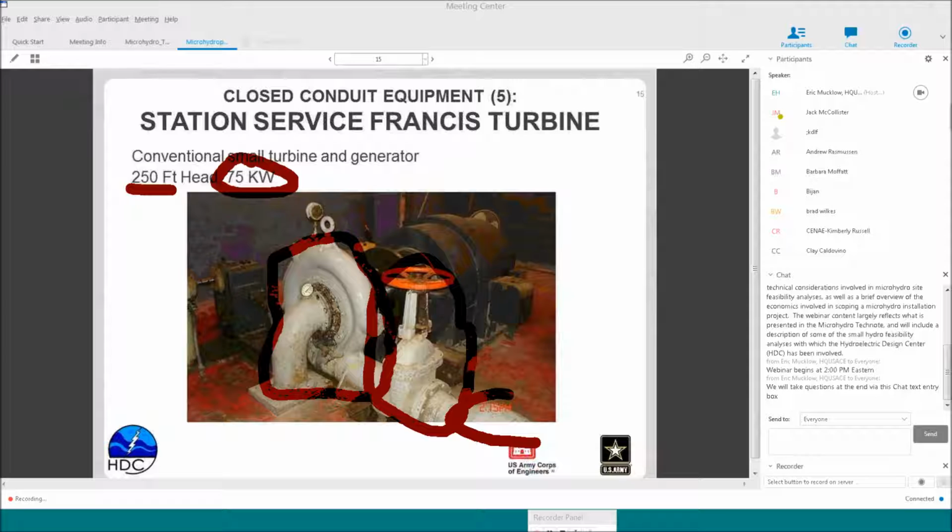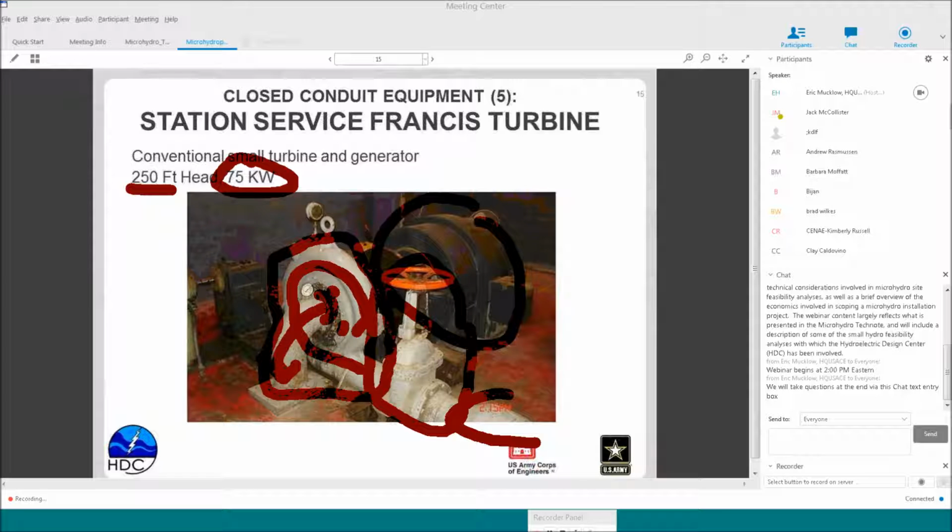The actual rotating part of the turbine we refer to as the turbine runner. The water is directed in, wrapped around in what we call the scroll case, moves through the wicket gates, and then into the turbine runner here, which discharges in this direction. Off to the right here, this black piece, the black housing, contains the generator, and there's a governor at the left here that is going to control the output of the generator by controlling the flow through the turbine.